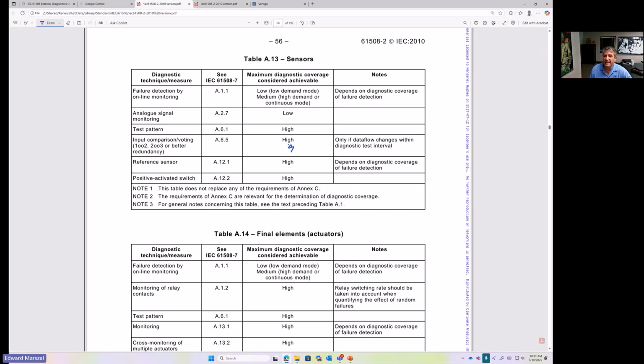So the quality of your measurements is not the same, and there could be a lot of discrepancy between the signals just based on the different components you have, the different maintenance activities and maintenance records that you have, and then the external stuff like signal conditioning, differences in locations, differences in elevations. There are a lot of things that can cause those two transmitters to read different signals other than a failure of the device.